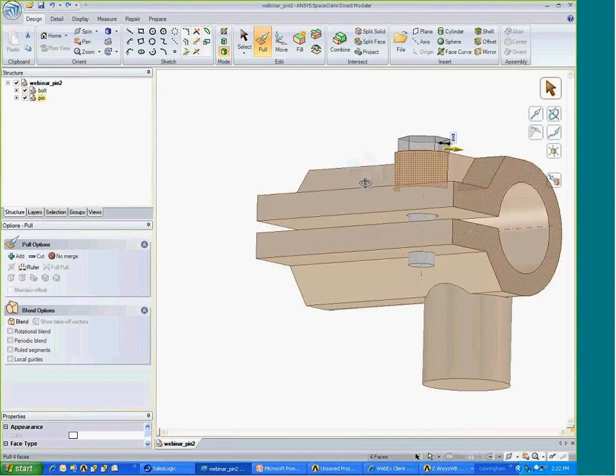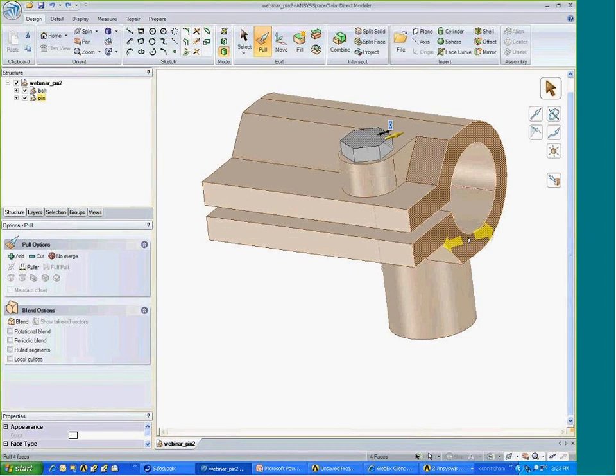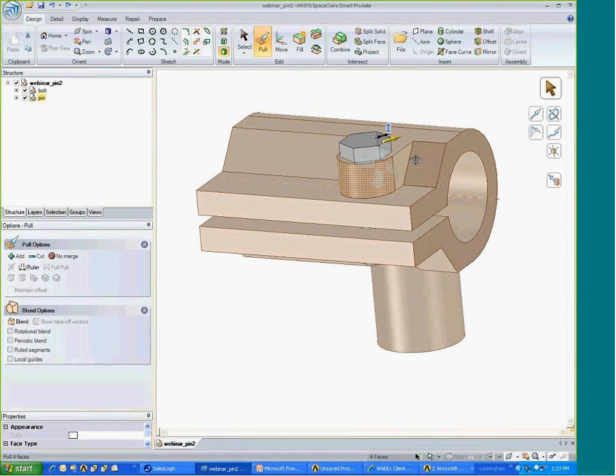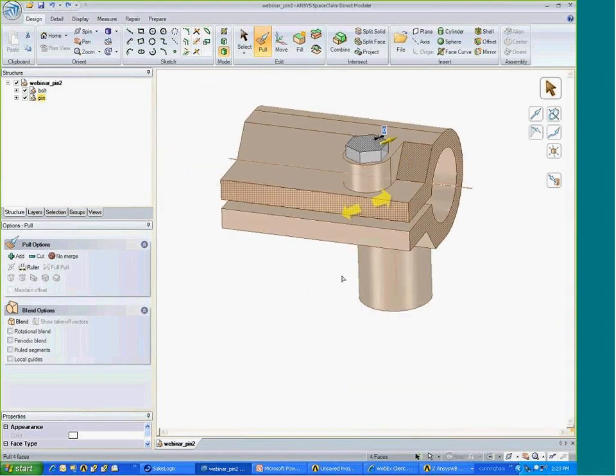Additional advantages, you can take these parametric operations into the parameter manager on the Workbench side of the equation, and you can drive those parametrically from Workbench once you've established the parametric features on the SpaceClaim side. In addition to that, if you were working with a non-parametric file, something like a SAT file or an IGES or Parasolid file, any morphing operations that you make on the geometry in SpaceClaim can be driven parametrically with the Workbench environment because it does associate directly with the parameter manager inside Workbench.